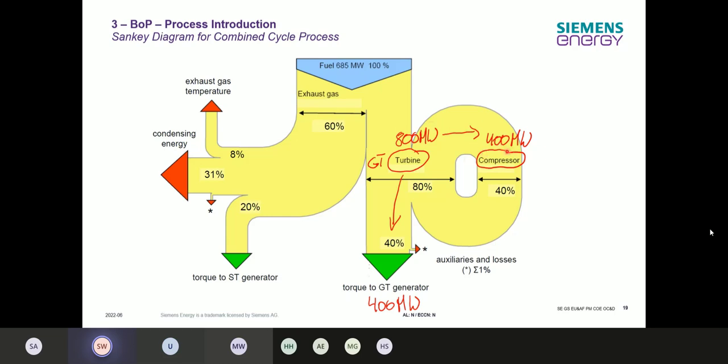For the gas turbine, the goal is always to keep it internal, because an external system could fail, and then you're running your turbine without a compressor, and this will lead to a lot of damage on the turbine because you also have cooling lines in there, cooling the blades, etc. So you want to keep it internal, and of course the engineers are trying to increase the efficiency here.